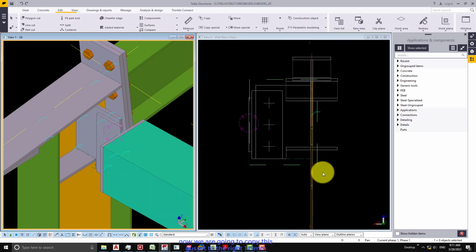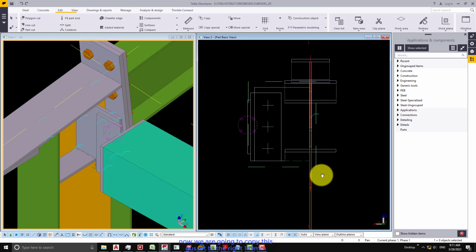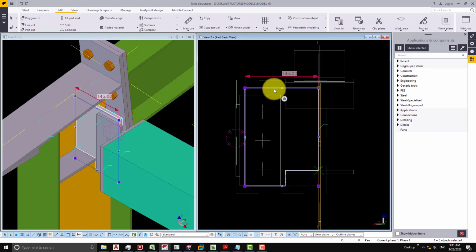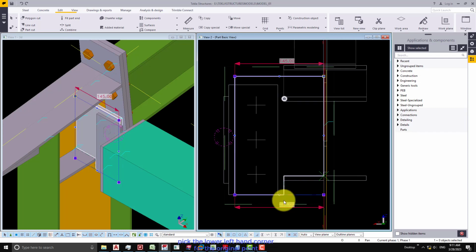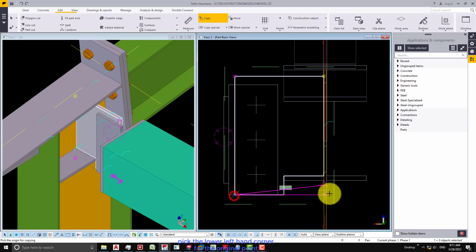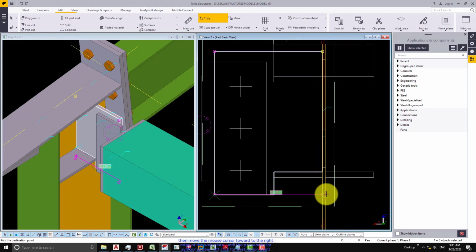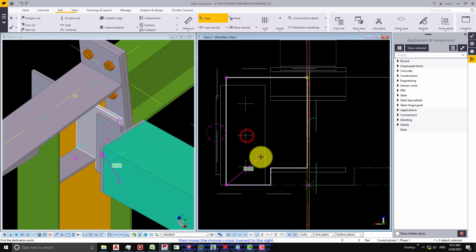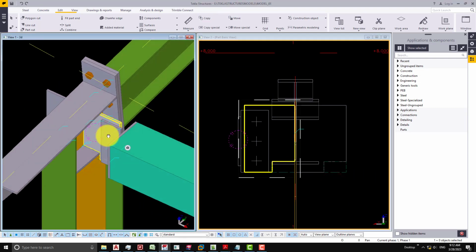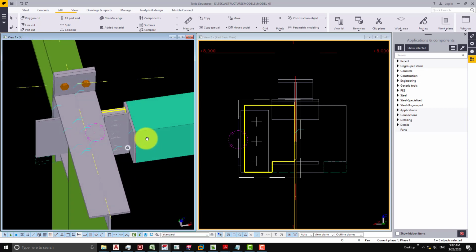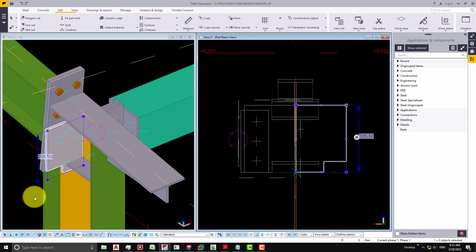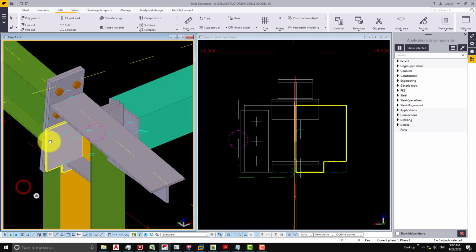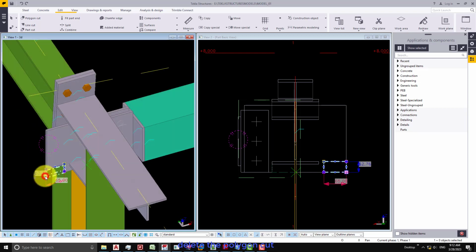Now we are going to copy this gusset to the right 149 mm. Select the gusset, then press Ctrl+C to copy. Pick the lower left-hand corner for the original point. Then move the mouse cursor toward the right edge of the web plate until the perpendicular symbol appears, left-click for the destination point. Delete this polygon cut.